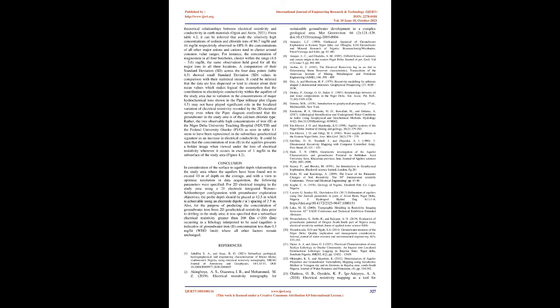In Profile 5 of the Federal University Otuoke study location, FUO5, see Figure A2, the water-bearing sands occur at a depth range of 10 to 12 m with iron concentration of 1.64 mg/L, which was the highest recorded groundwater iron (Fe2+) concentration in the study. On the other hand, Traverse EFP10 in the Ikaki floodplain, Figure A2, recorded the highest resistivity, 273-377 Ωm, coinciding with 0 iron (Fe2+) concentration, where the major water-bearing sand unit occurred at a depth range of